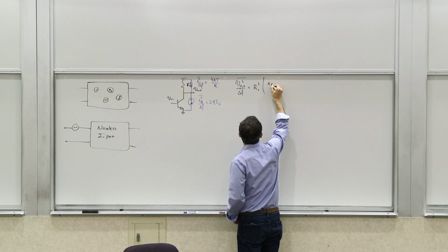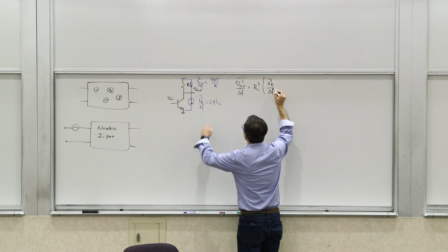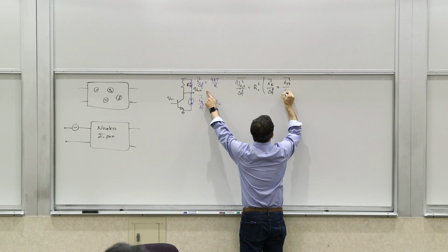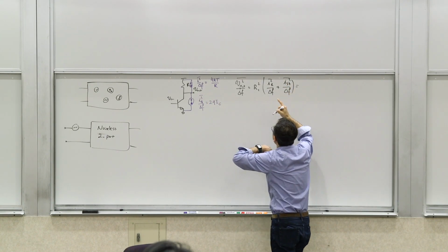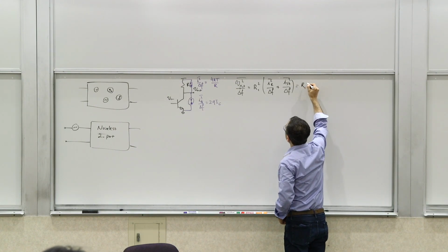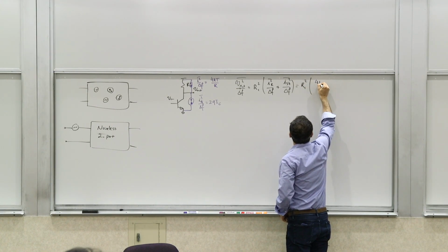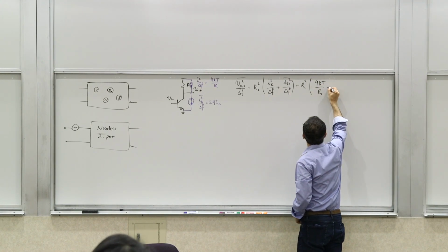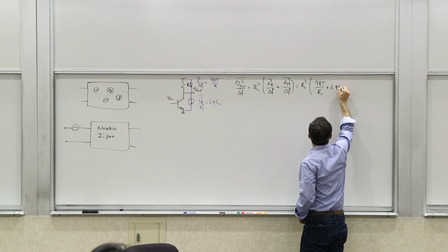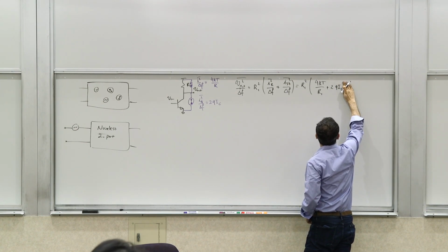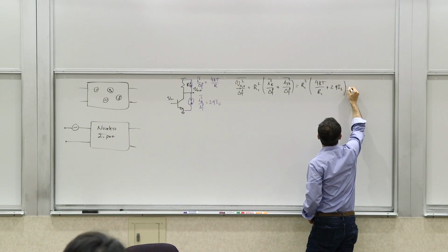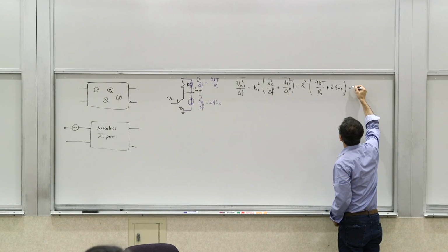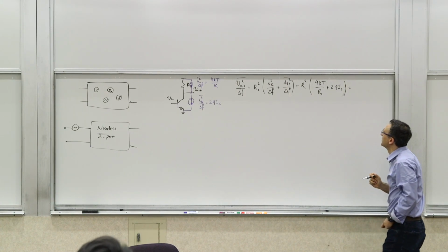So basically, you have I R delta F, the noise of this resistor, plus the power of that, plus the shot noise, current shot noise power at the output, and then you can plug in values. So you get R1 squared times 4kT over R1 for that one, and then you get 2qIC, the DC bias current in the transistor. So you get that, and then if you go and simplify it, well, let's keep it the way it is right now. It's okay. So that's that.